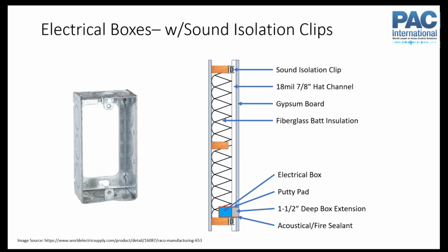So the clips and the hat channel, or a resilient channel or whatever is there, are there to isolate this drywall from the stud, so we don't have a rigid connection there.